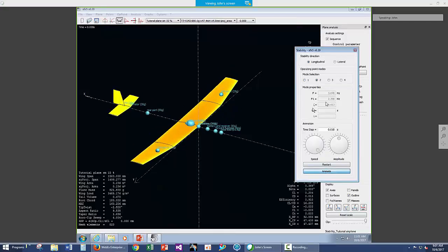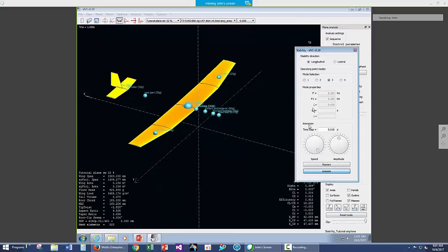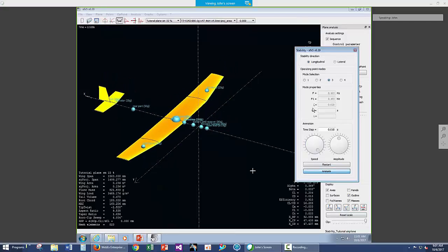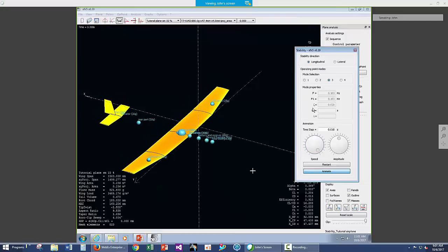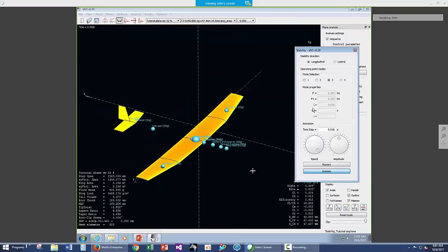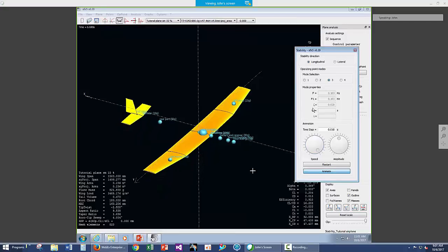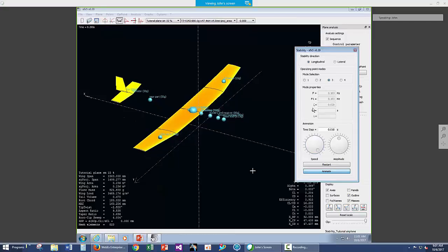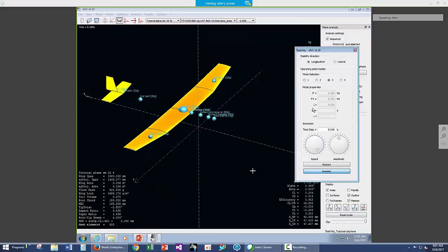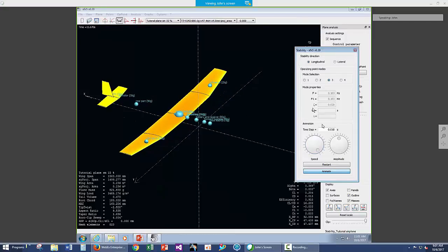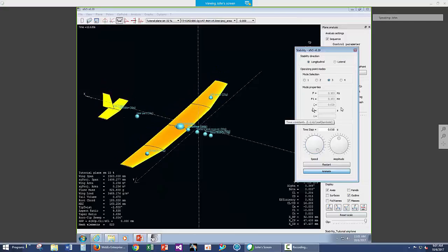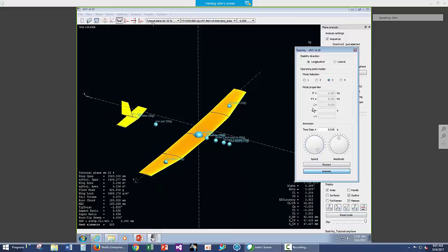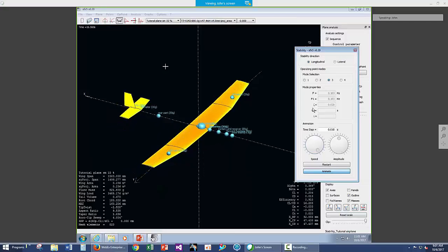And then in the longitudinal mode, we've got the phugoid motion. And this is a phugoid motion in the coordinate systems of the airplane. This is the one when you throw your glider here later in the semester, you will see it wander up and down until you get the CG in the right place. This gives you some of the characteristics of that, the natural frequency and the damping coefficient, other parameters. All the inertias are contained in a log file, which is up here.